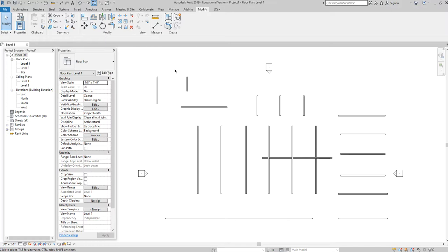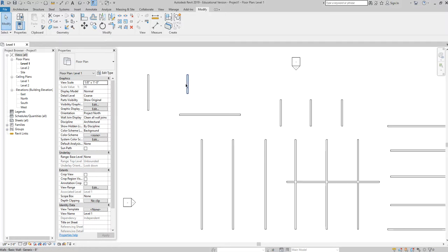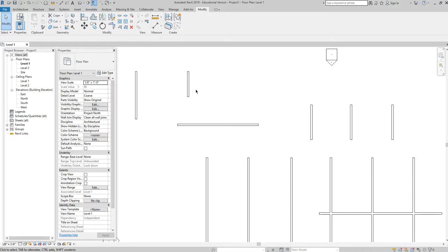Align will allow you to take one object and align it with a second or a third or a fourth. It can be a singular type command, or it can be one that you do over and over and over again. All right. But essentially, let me just show you how it works, and then we'll talk through it. AL, click, click, and one aligns with the other. Okay. Wouldn't those of you who use AutoCAD, wouldn't this be wonderful in AutoCAD? Right?